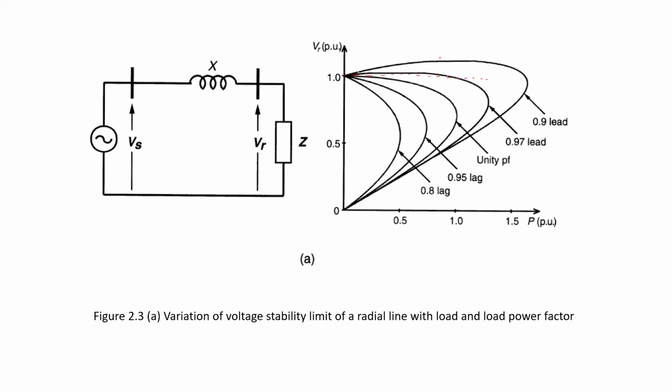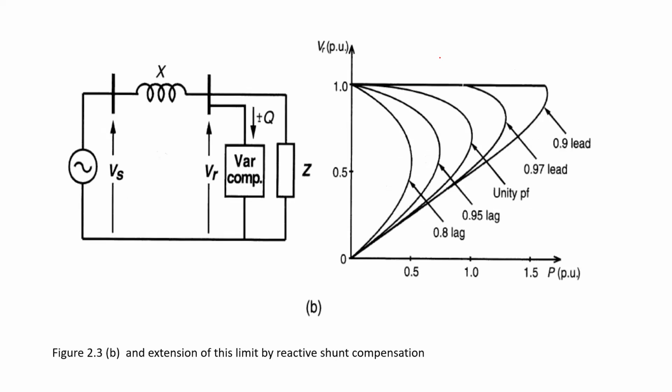So because of the surplus of reactive power, the voltage increases, isn't it? But we do not want this; this is not our desired characteristic. Therefore, we have connected a shunt compensation at the load side. So this is the shunt compensation. This may be a thyristor switched reactor, isn't it?